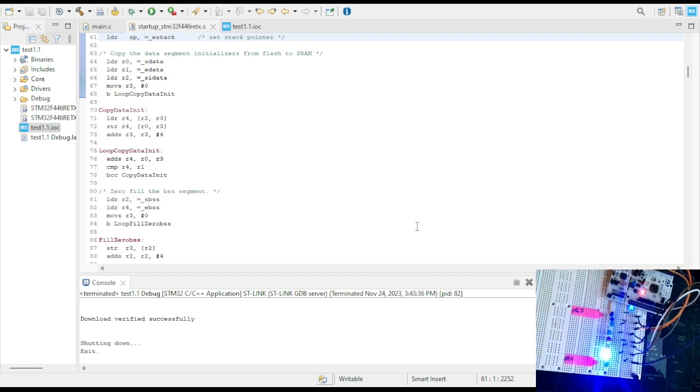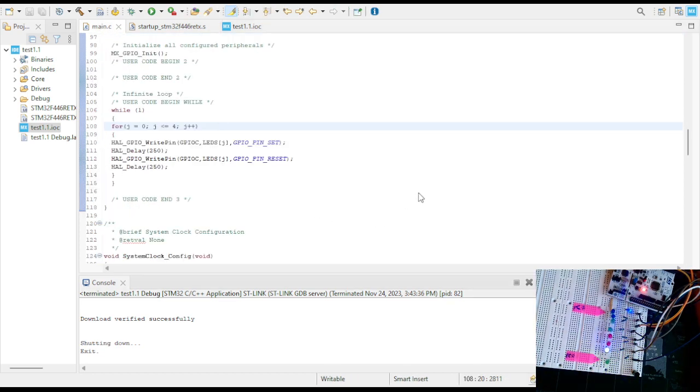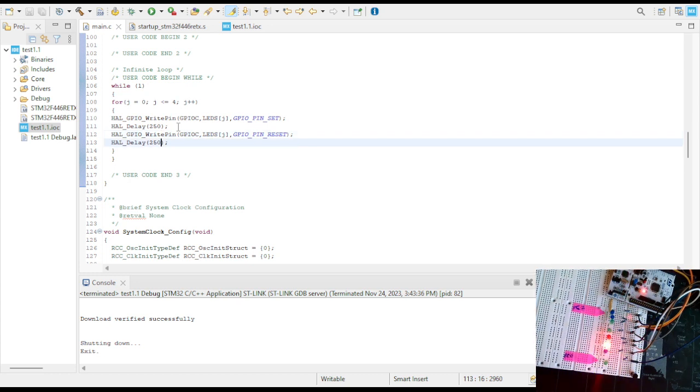Okay, but let's say that they're going too quick for you. They're moving up and down too quick for you. You can come here and you can play with the delays. You can increase the delay here. Let's first increase the delay that is off. So let's say that it stays on before any change, before it moves up, and by up I mean to 5. I want it to delay, let's make it really clear to see the change, 10,000 milliseconds.